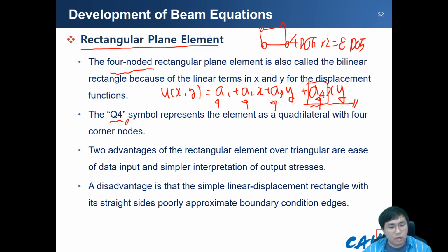So we are going to discuss the rectangular element in more detail. This rectangular element has some pros and also some cons. First, the disadvantages compared to the triangle element: it has a slightly nonlinear displacement, which makes the integration of the local stiffness matrices more difficult, and it needs one more nodal point.